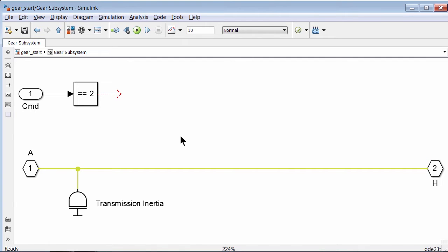However, there are no mechanisms here to couple or decouple the power input. These mechanisms would be needed to model multiple gears. In automotive systems, this is achieved using clutches, which push multiple flat plates so that friction decouples or couples the power input. These types of models are available in Sim Driveline.